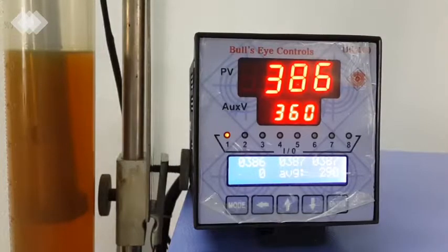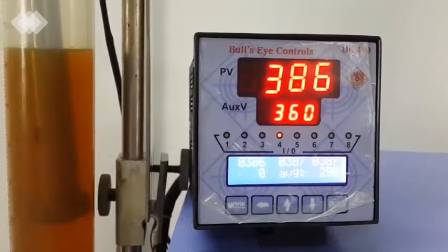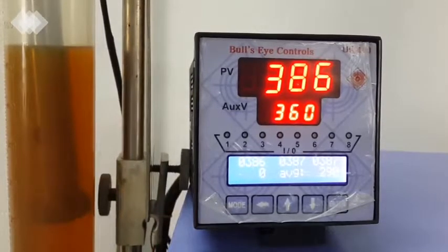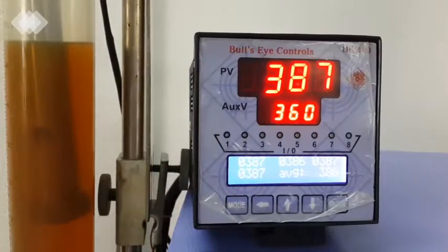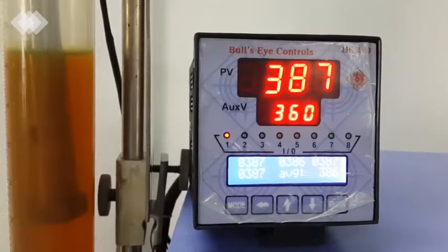Sometimes, due to some reason, the sampling does not take place, maybe because of lack of air pressure or some other reason. Then how does the instrument restart? How does it sample by itself? There is a value in the parameters where the period is entered, and if there is no new reading in that period, the instrument again attempts to restart. And if 3 such attempts take place and it is still not able to restart, then no operation comes and an alarm comes. So that's how it happens.